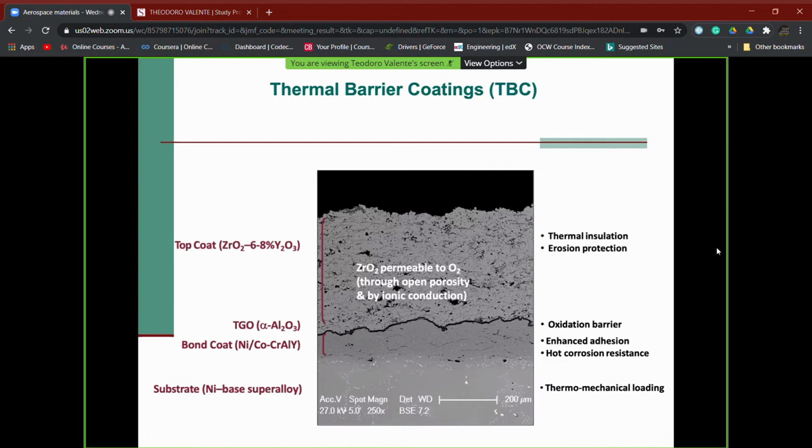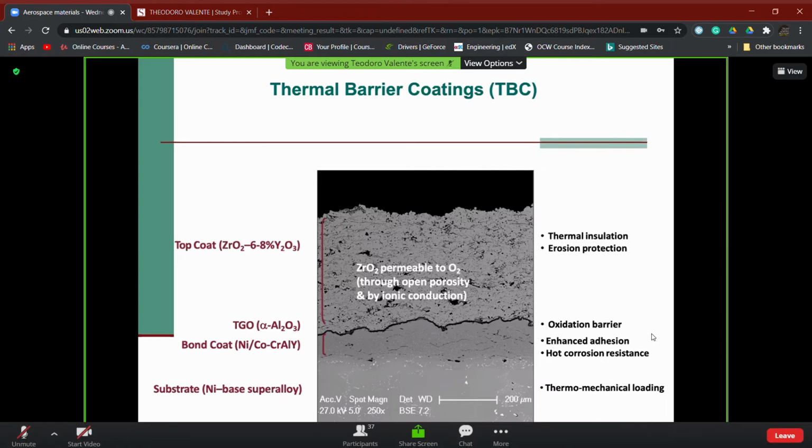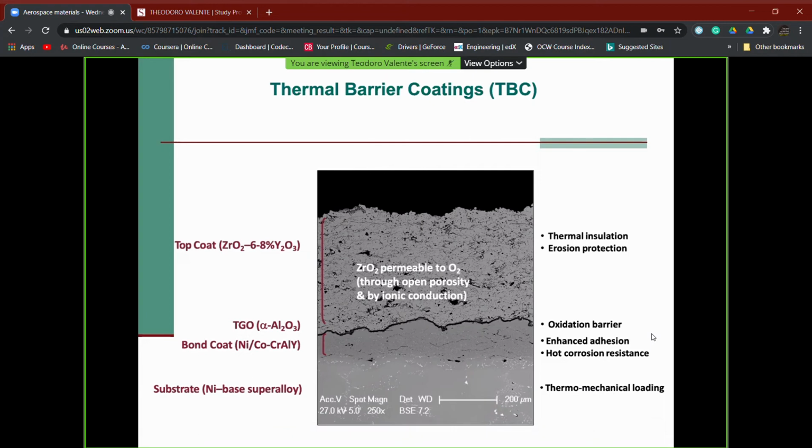Silicon carbide, reacting with oxygen, can form silicon oxide, which is the basic constituent of glasses, and then can form carbon oxide or carbon monoxide, depending on the partial pressure of oxygen, which is also a gas phase, and thus silicon carbide is deteriorated by oxygen at high temperature due to a direct reaction between the constituent elements and oxygen present in the working atmosphere.